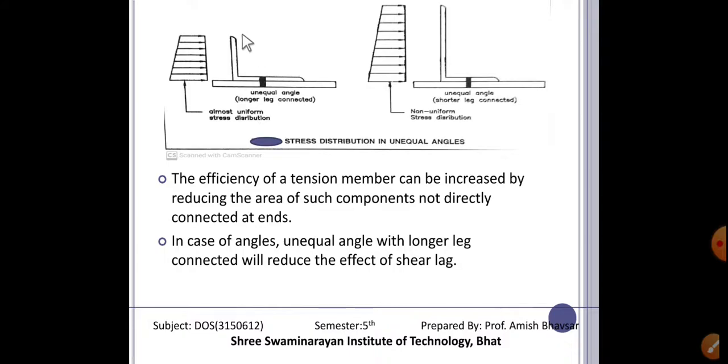This member angle is connected with the plate, and whenever the stress is going to develop from this bolt from here to here, and it is from here to here. So, whenever the stress is distributed toward both sides, this portion must be affected earlier at FU, and still it is because it is long, so still it is in yielding, then this portion must fail as early. So, it is called block shear failure.